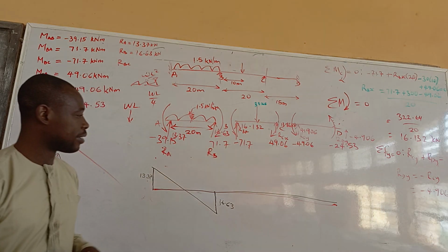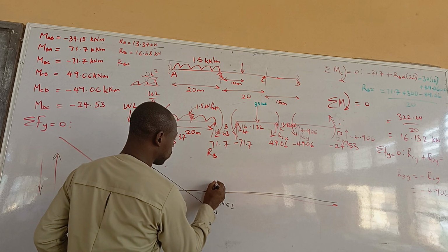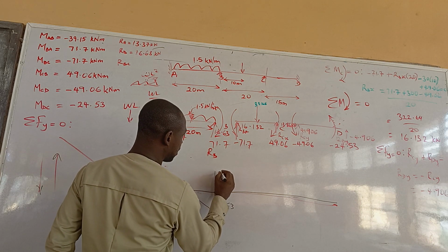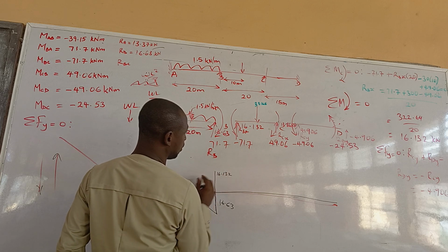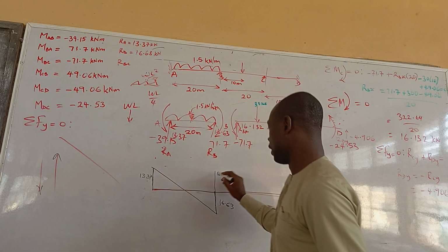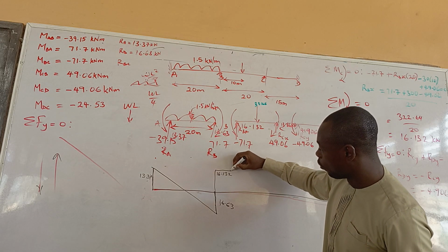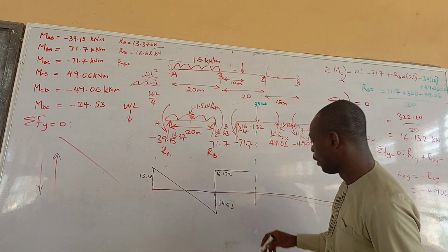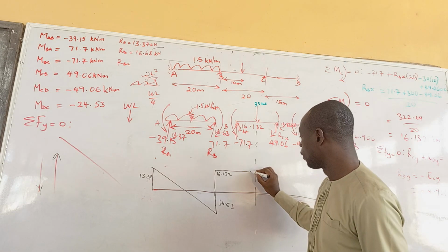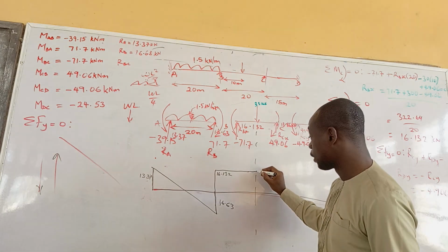Now, at this 16.63, there's something I want us to look at. At point BX, it travels 16.132. So we have to travel 16.132 to this side. Now, this 16.132, I continue to move straight until I get to this point load. That point load is what? 30 kilonewton, right? Yes. So I have to drop 30 kilonewton downward here.